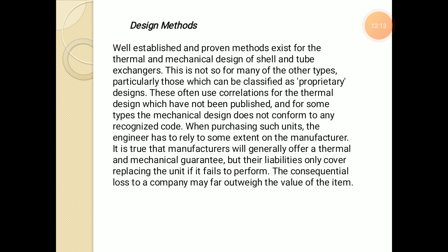So the method that we adopt while designing a heat exchanger plays a very important role. Simultaneously, thermal and mechanical design has to be considered. One example I would like to mention once again: when fluid flows through both the shell and tube sides of a heat exchanger, the tubes sometimes vibrate. That vibration analysis has to be done while designing the heat exchanger. So the design method is also a part of the selection of a heat exchanger.